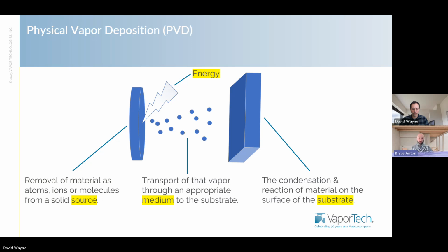By physical vapor deposition, I mean that we're starting with something physical, meaning a metal target material, usually a metal like titanium or zirconium. We remove atoms of that metal by some kind of energy, and we do this in a vacuum, for a number of reasons, mostly to be able to control energy and reactions, and because the plasma processes that we use to evaporate or remove material require low pressures to be stable. The material starts in a solid form, gets evaporated, and becomes a vapor. It travels through the vacuum until it condenses and lands on the parts.